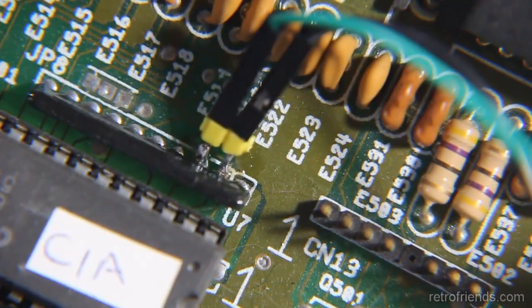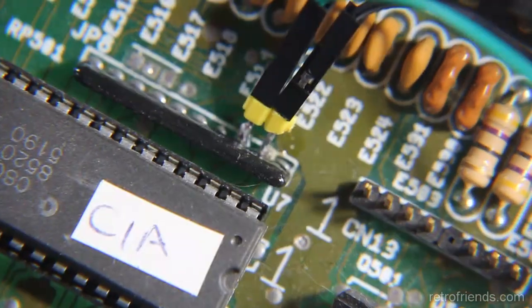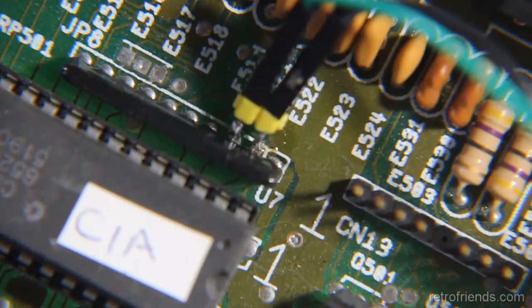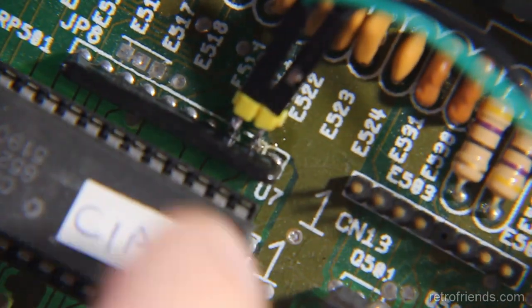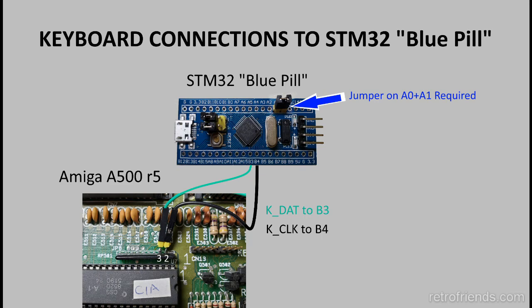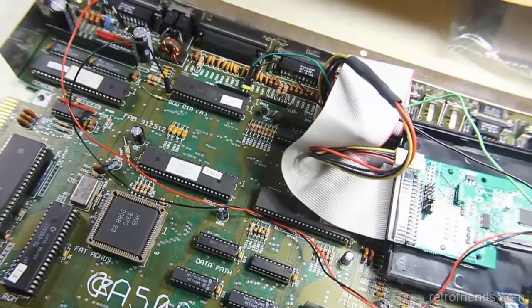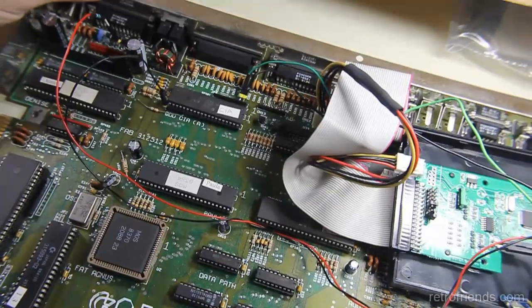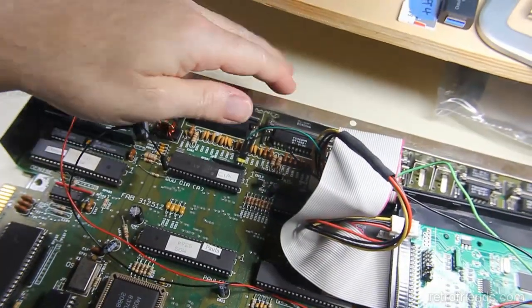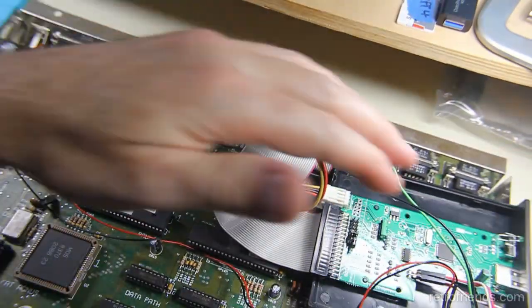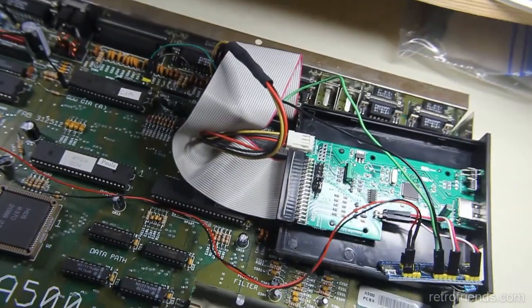So that's RP501, which has pull-ups for the keyboard. These are all pull-ups for the keyboard, or pull-downs, I don't remember, probably pull-ups. And pins 2 and 3 are the keyboard actual data and sync signals. So anyway, that's all we need. Now I just need to hook up a video output and a keyboard and power, and put a thumb drive in the Gotek and test it out.